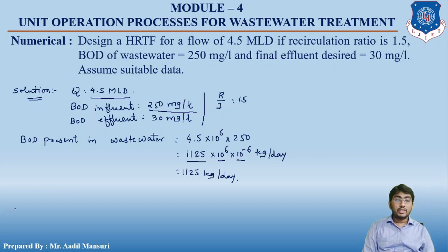Now the next step is to assume BOD removal in the primary sedimentation tank. So assume BOD removal in PST equals 30%, say.